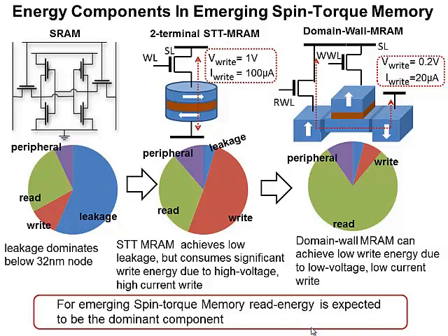Apart from energy consumption, there are of course other challenges which the SRAM technology faces. And most of those are related with variability issues at scaled technology nodes. In the last decade, several post-CMOS technologies have been explored as a drop-in replacement for SRAM. And one of the most widely accepted drop-in replacements for SRAM has been identified as MRAM technology, or STT-MRAM technology. STT-MRAM stands for Spin Transfer Torque Magnetic RAM.